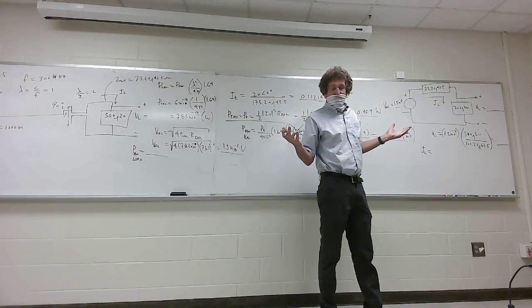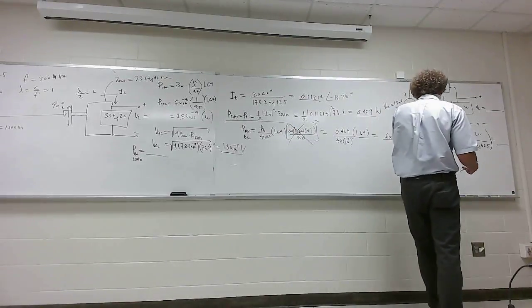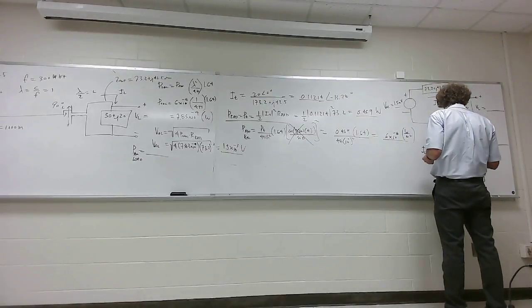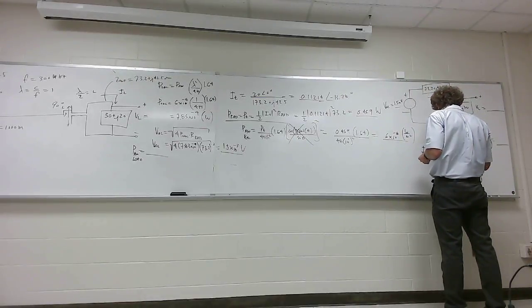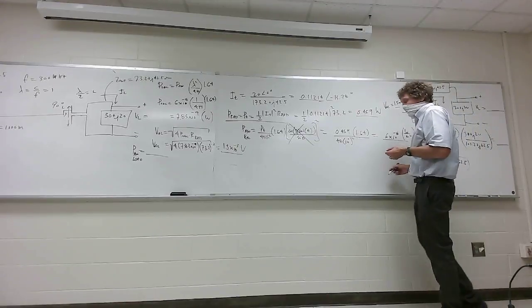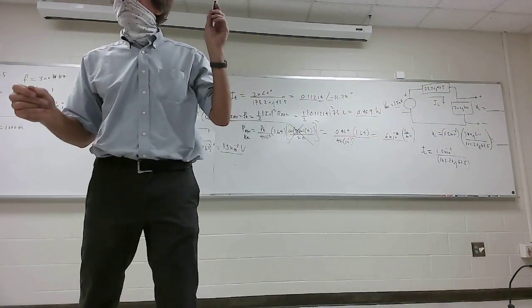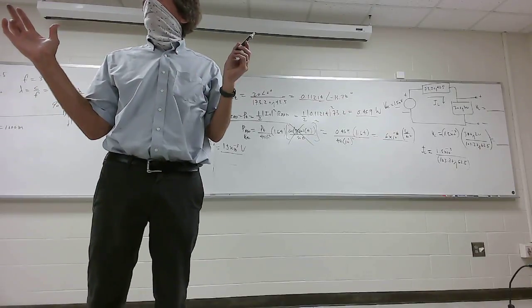VOC over, just voltage, right? VOC over the sum of the series impedances, right? So this IL would be equal to what? 1.5 times 10 to the minus third over 103.2 plus j62.5. Do you all agree with that? Did you have a question? If you do, please ask. Y'all follow me what I'm doing here?